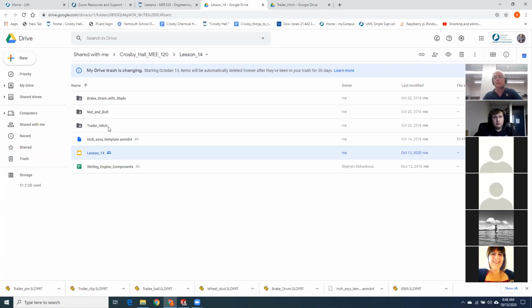Okay. So if you did renaming it with the drawing closed, that's a huge no-no. And that's what they're probably griping about. Okay, so when can you rename it? Just when you have the drawing open? Exactly. In that case, you want to do something like a save as, and then you can rename it whatever you want, and the links will all remain established.